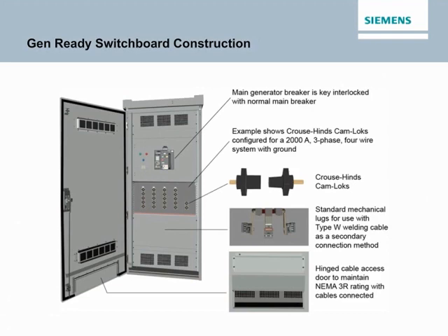The generator breaker can be connected to the normal main switchboard by cable in retrofit applications or hard bus in new construction applications. The generator breaker is key interlocked with the main breaker in the normal switchboard lineup. The switchboard can be rated suitable for service entrance.